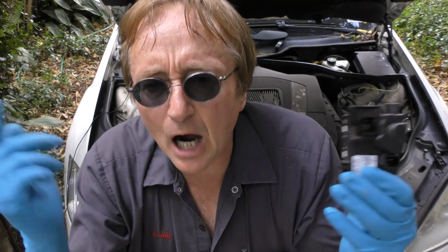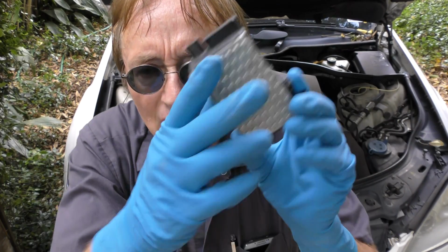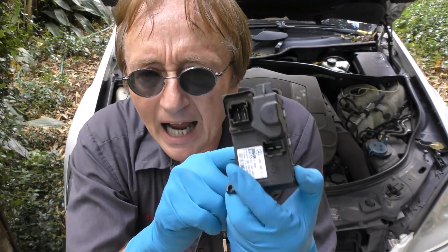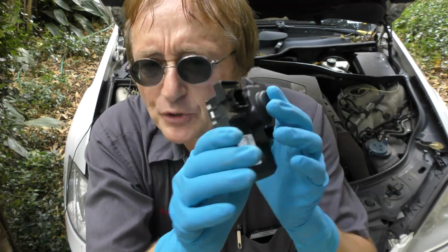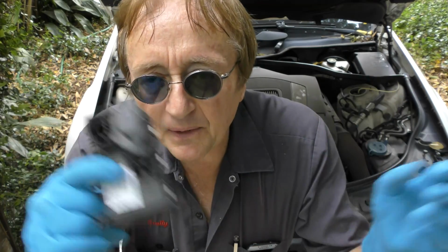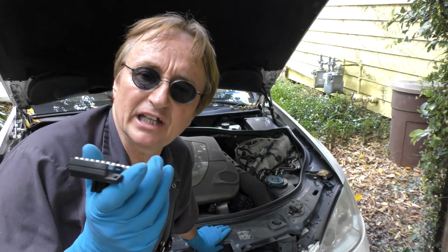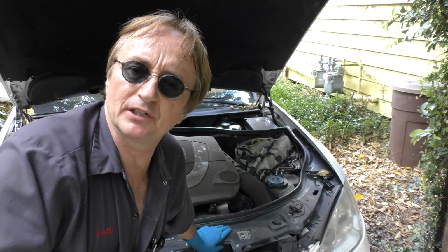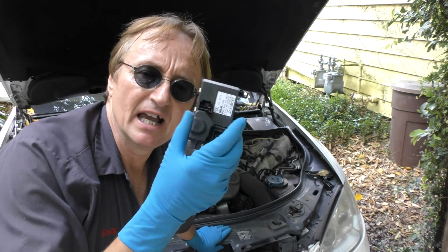So we're going to get a new motor for it, but on this Mercedes, realize this stupid computerized resistor often goes bad. We're probably going to change that too, but we'll change the motor. And then if it doesn't blow with that, we'll have to change the resistor assembly too. And really, personally, I find it kind of amusing that a car that originally cost $112,000 has such cheap parts that don't last so long.